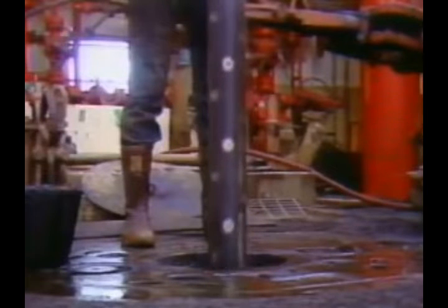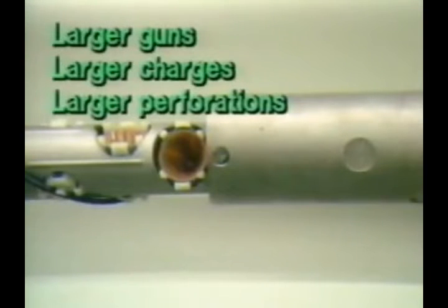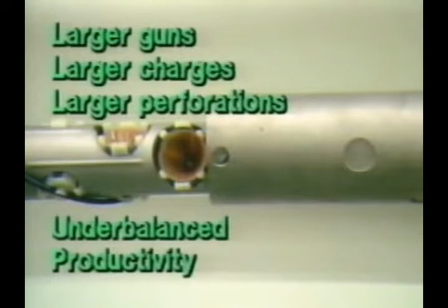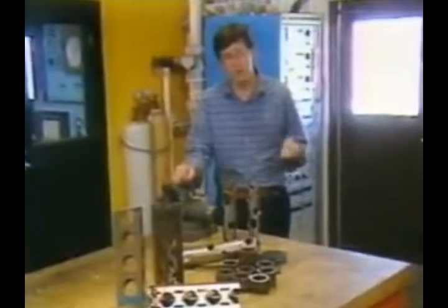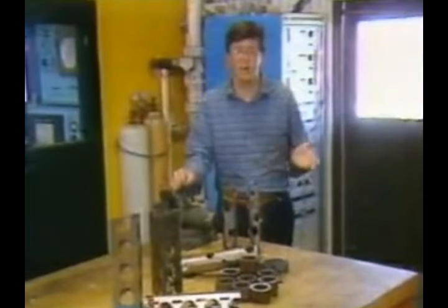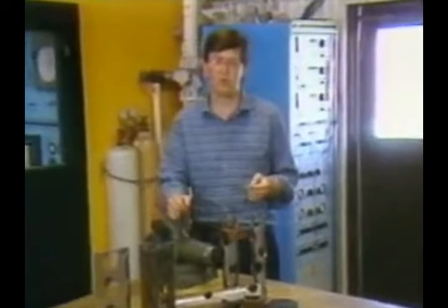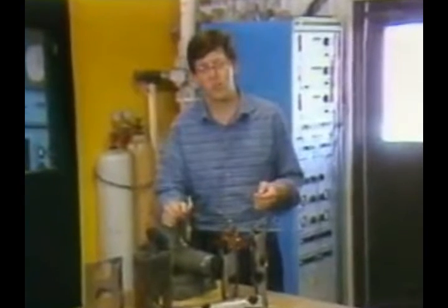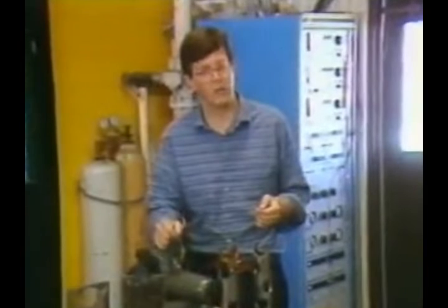Tubing conveyed perforating seems to provide a means to combine both the larger high-performance guns with the flexible pressure conditions. So we see that in considering just these perforating features, wireline versus tubing conveyed, overbalanced or underbalanced, retrievable or expendable guns, we already can come up with at least a dozen different useful design combinations to choose from. All this is without yet considering the variety of shape charges available.